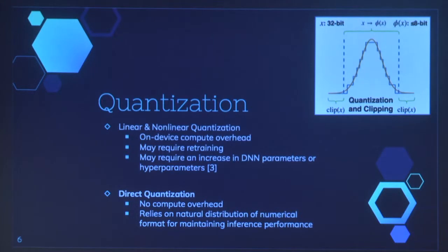You could do neurogenesis. You could do all kinds of tricks, different plasticity models to optimize these networks. And one natural fit is, a lot of folks have also been looking at low precision implementation or low precision arithmetic in implementing these on low-end embedded platforms. When we're talking about low precision arithmetic, a lot of earlier research has shown how much energy or power savings you could have when you move from a 32-bit floating point to an 8-bit floating point. It has been shown that you could have 4x reduction in the data movement cost, and also 4x reduction in the compute resource utilization. And that is significant savings when you're moving from 32-bit to 8-bit.